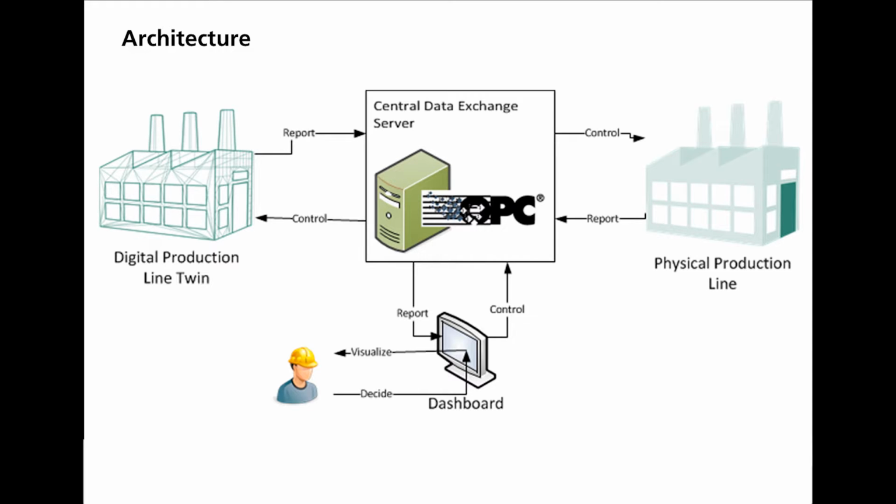The physical modules and their digital twins currently exchange information and data using a central OPC server. This is one industry standard that is very suitable and easy to implement because a mechatronics concept designer as well as most industry PLCs provide the interface. It also allows for easy access of the data either on-site or from remote, using one of many applications for mobile phones or any Windows-based PC, up to using Microsoft Excel to push dedicated information cyclically onto the responsible's Office PC.